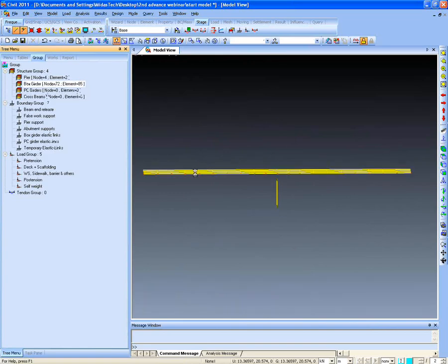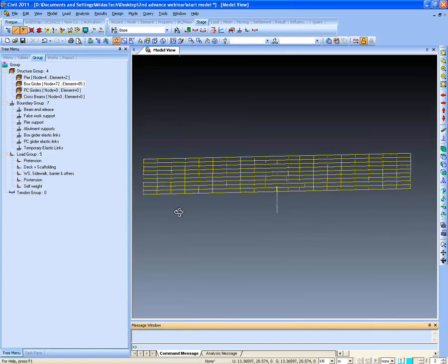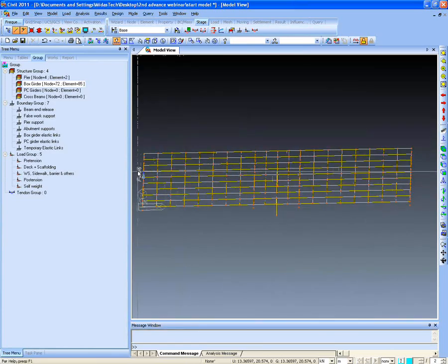Now I will select the precast girders, but here I would like to tell you that the cross beams that I have made are to provide the structure rigidity or stiffness in the transverse direction, because the deck will be continuous.